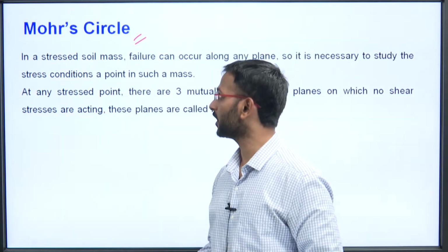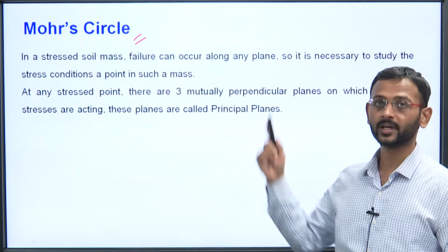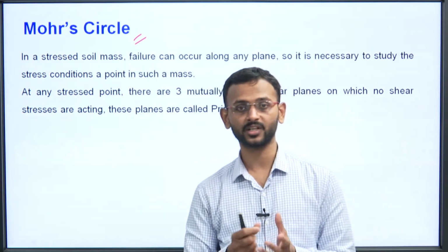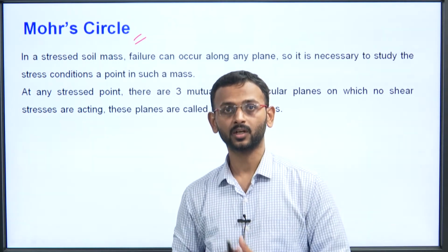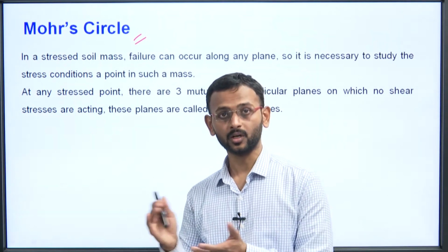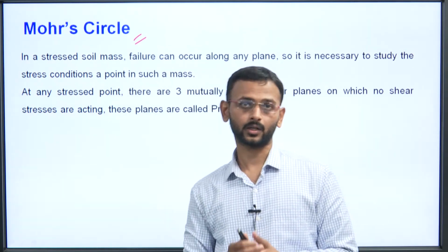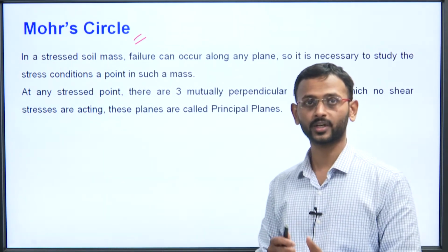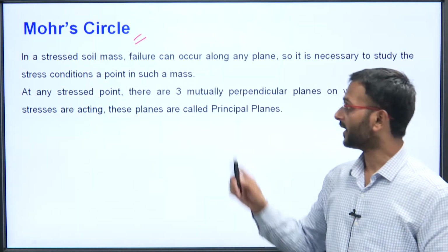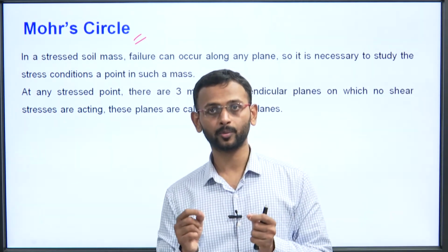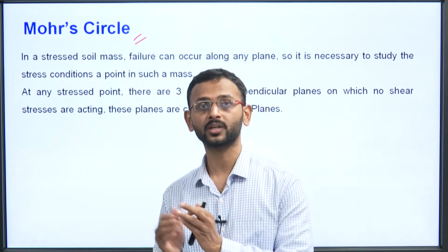So in a stressed soil mass, failure can occur along any plane. So, it is necessary to study the stress conditions of a point in such a soil mass, or any mass, you say that in engineering mechanics or SOM you have studied it in different aspects there. At any stress point there are 3 mutually perpendicular planes on which there are no shear stresses acting.